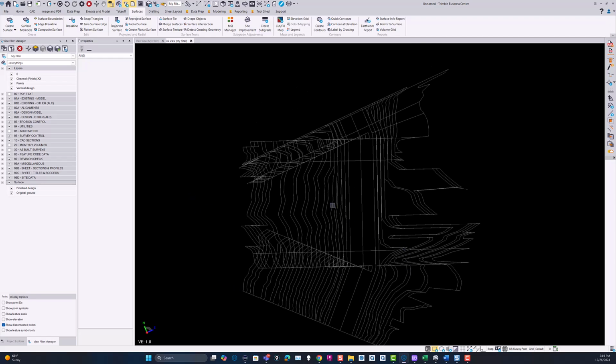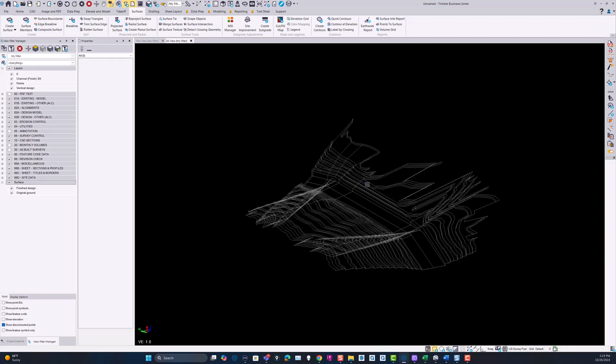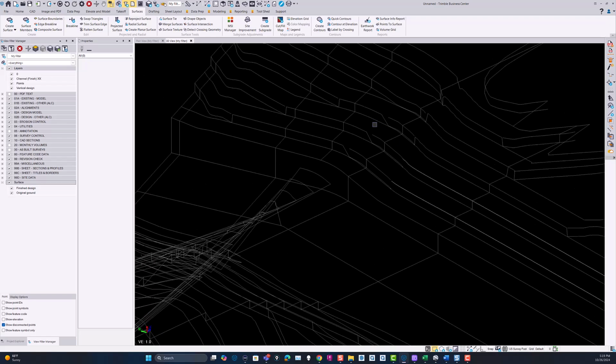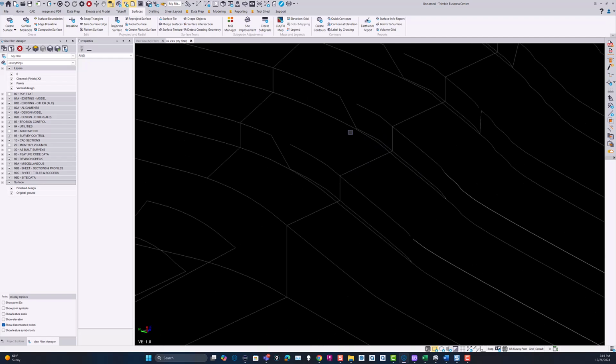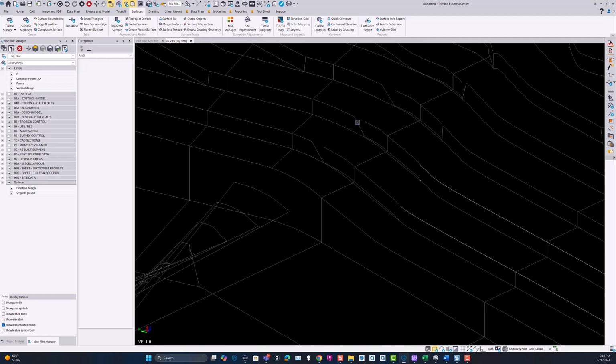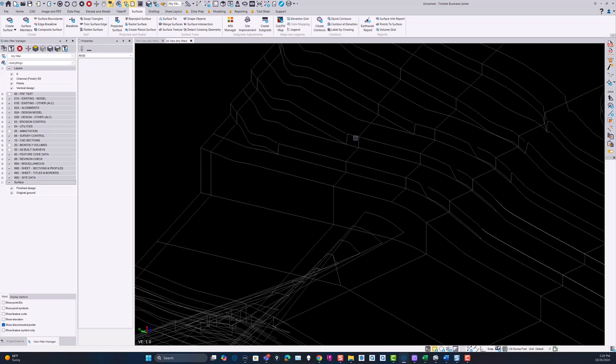not only do you get these wedge problems, but if you take a look at this, the data over here, you'll find that when this calculates, because of the way the ground is working, sometimes the elevation projection calculates here, and then sometimes it projects down here. You'll find that you get maybe double lines in some places. You'll get these little sloping lines coming down. It gives you a lot of segments like these ones here and here and here you need to remove.